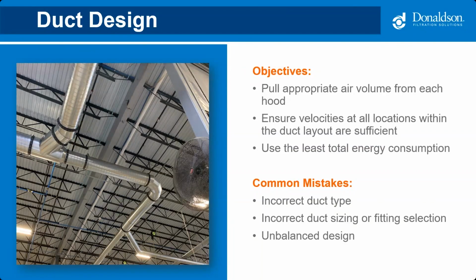So a few common mistakes that I see when it comes to duct design typically would be the incorrect type of ducting being used, the incorrect duct sizing or fittings being used, and the duct system not being balanced correctly.